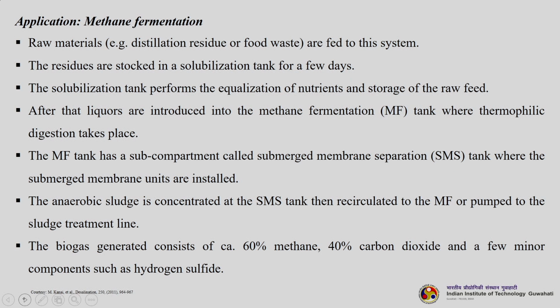Then another application is methane fermentation. So, here raw materials, basically distillation residue or food waste, are fed into the system. The residues are stocked in a solubilization tank for a few days to let them solubilize, basically stabilize. So, the solubilization tank performs the equalization of nutrients and storage of the raw feed. So, after a few days, the liquors are introduced into the methane fermentation tank, where thermophilic digestion takes